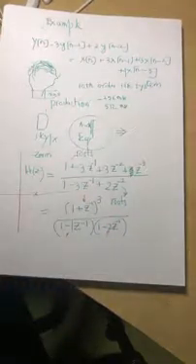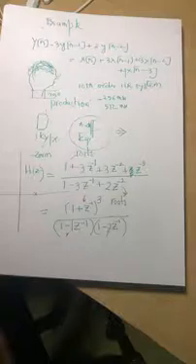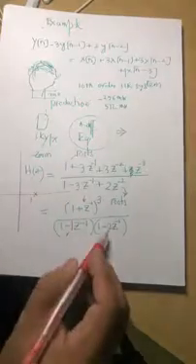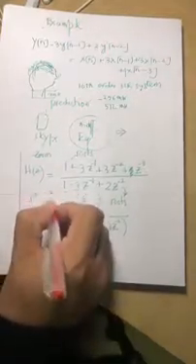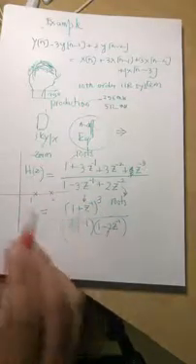A pole on the unit circle means that whether it is a left-hand side or a right-hand side sequence, this can never be stable. So it's not a stable system. One pole is here and the other pole is at 2, and there are 3 zeros at minus 1.